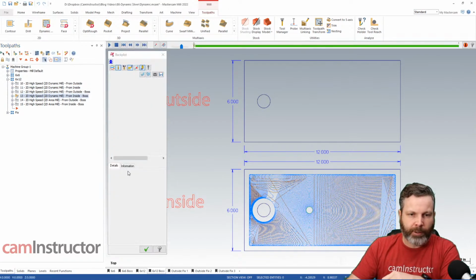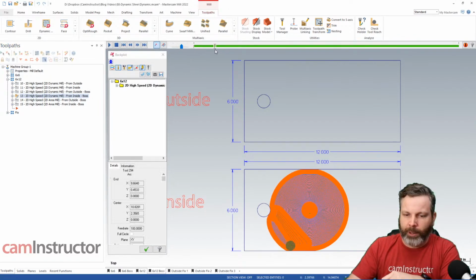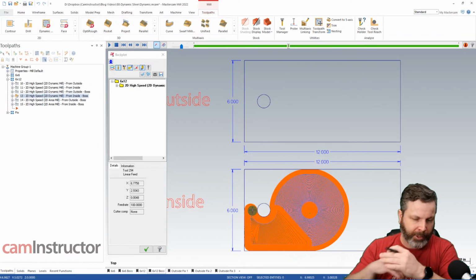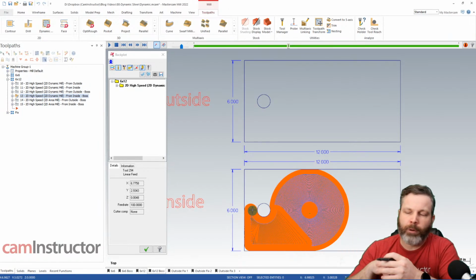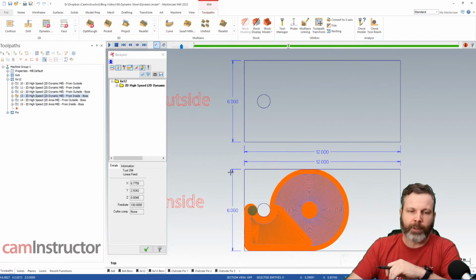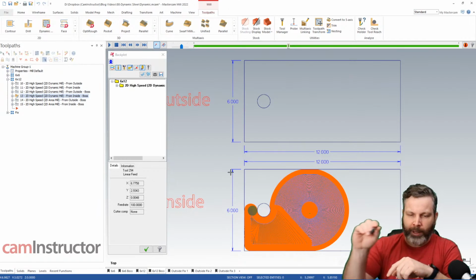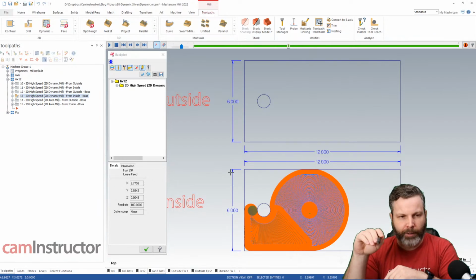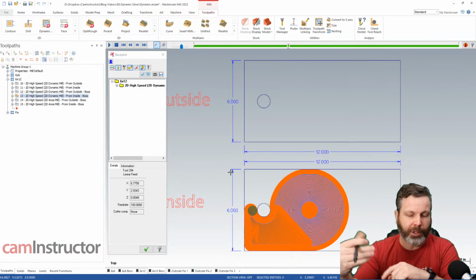is right here. So we're into our part, we're cutting away, everything's great, grand, groovy, another G word there we go. Until we get up into this section right here. What can happen here? Why is this a problem? Okay, so as I mentioned, we've got a 3/4 inch tool. We programmed it at 100 inches per minute. So that 100 inches per minute, when we're doing a straight line, the cutter is getting a consistent chip load. When we start to do arcs, the chip load actually changes.